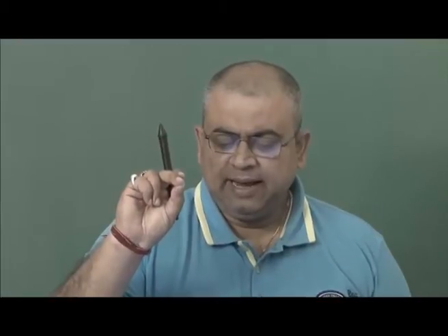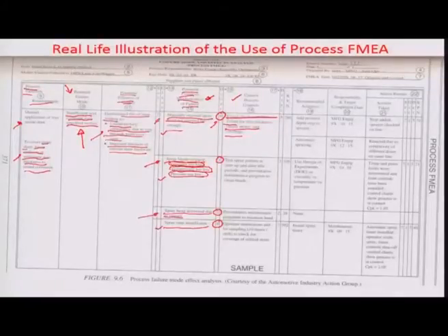Also, the coverage can be measured by moving the pointer from one side of the door to the other to see if the whole layer is executed, or if there is some kind of hole or crevice in between which has been left, or if it is insufficient at certain times because of beading and other effects. So only a visual check is initiated at this particular failure mode for process control.